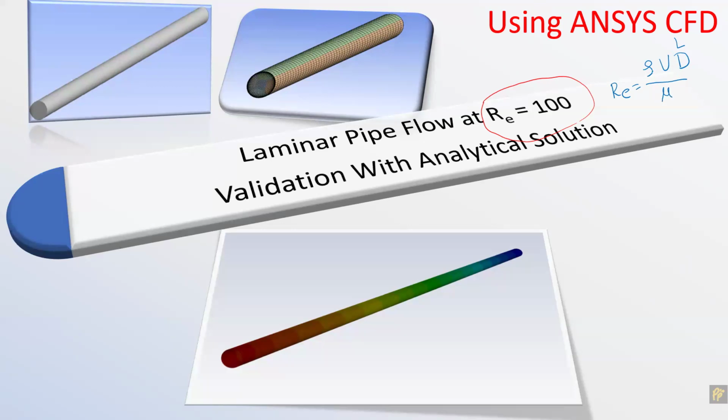I will discuss these things in detail. So we have to actually input these four parameters into our CFD simulation. The density and the viscosity are fluid properties. Velocity is a flow property, and the diameter is the geometrical parameter that you will get from the geometry modeling. So these four inputs are required when we decide about any CFD simulation.